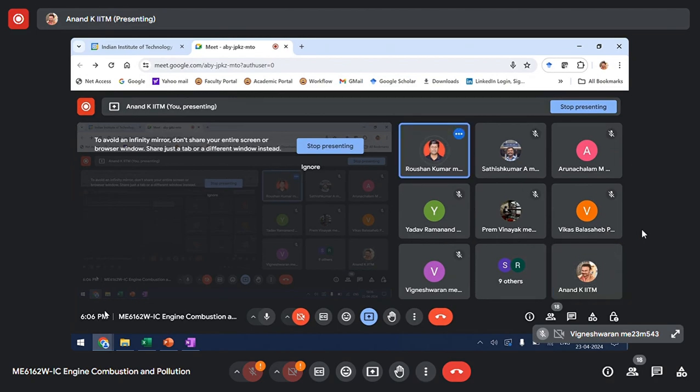Okay, sir. This is where the problem comes, because of the trade-off between NOx and PM. But NOx levels are almost comparable for SI and CI. In SI, you don't have a PM control problem. In CI, you have a control problem. Also, there is a trade-off between these two. Got it, sir. So levels are similar, but the trade-off is creating a problem for CI. The trade-off is what is complicating the problem of emission control in the CI engine. That's the core problem in the CI engine.